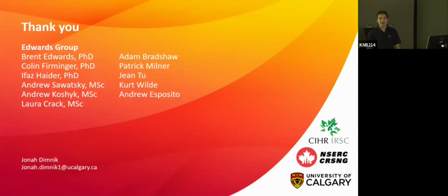So damage, if we go to the most fundamental definition, is really what I was talking about in those earlier slides. It's really just this accumulation of flaws in the material. So we're getting these cracks and voids. And when we try to create a damage model, we would simplify this down to a representative volume element. And in this representative volume element, what's physically happening is the bonds are breaking between the atoms in the bone, right?